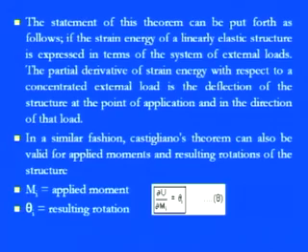So with those moments we can simply get the resultant rotations, and if we take the strain energy with respect to the applied load, we get the direct deflection. So we can simply figure out what exactly the deflection is and what exactly the resultant rotation is, based on the applied load and the applied moment.